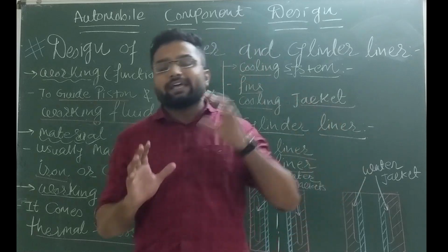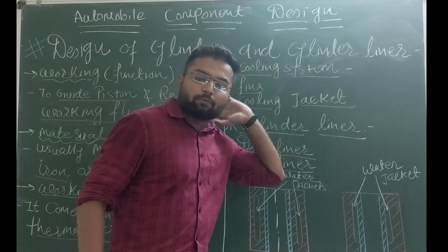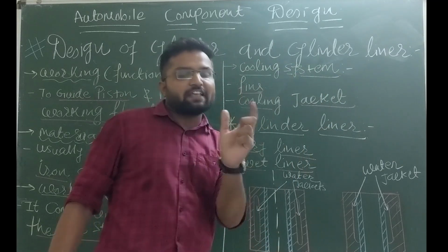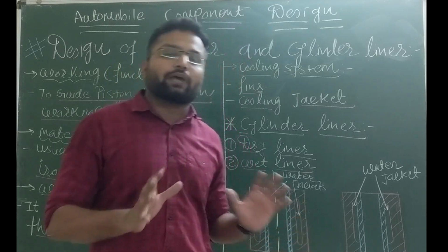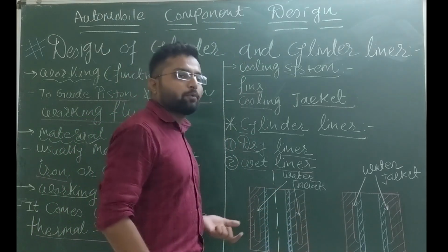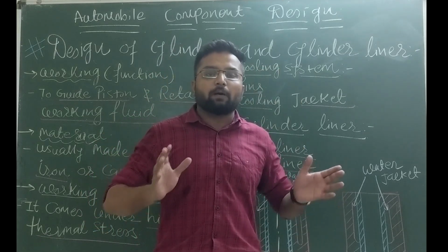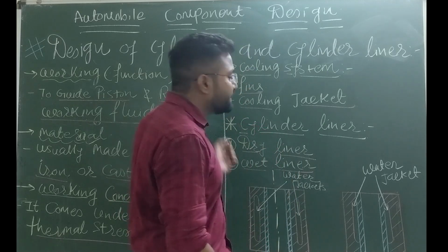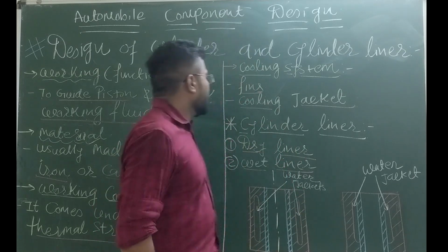You know that in a single cylinder type of engine, we are going to provide an artificial cooling system. In that, fins, when it is a low power engine, or you can say single cylinder engine, we are providing fins as an arrangement, or you can say design of a cylinder block. We are creating it in such a way that it can easily have heat transfer just depending on its geometry.